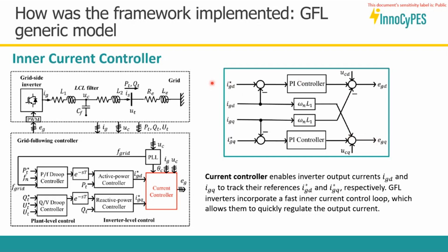So here again, we are using PI controllers because here we are also taking advantage of that DQ frame, right, in which the quantities can be represented as DC values. So that's why we can easily apply a PI controller in this case.